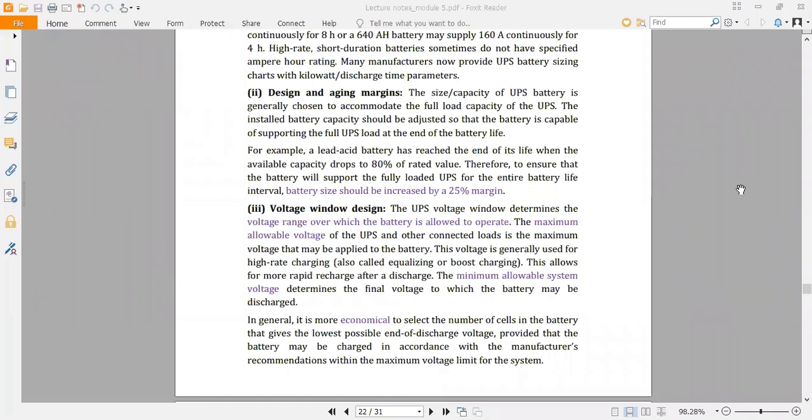ठीक है, बैटरी जिस रेट से डिस्चार्ज हो रहा है, या तो उसी रेट से हम लोग बैटरी को चार्ज करें या उस चार्जिंग रेट उससे ज्यादा हो डिस्चार्ज रेट से, तब क्या होगा हमारा कि हम लोग बैटरी के थ्रू लोड को पावर सप्लाई करते रहेंगे कॉन्टिन्यूअसली। अदरवाइज चार्जिंग रेट कम होगा, डिस्चार्ज रेट ज्यादा होगा, तो बैटरी विल नेवर बी फुल्ली चार्ज and we are not able to supply power to the load after a certain period of time.